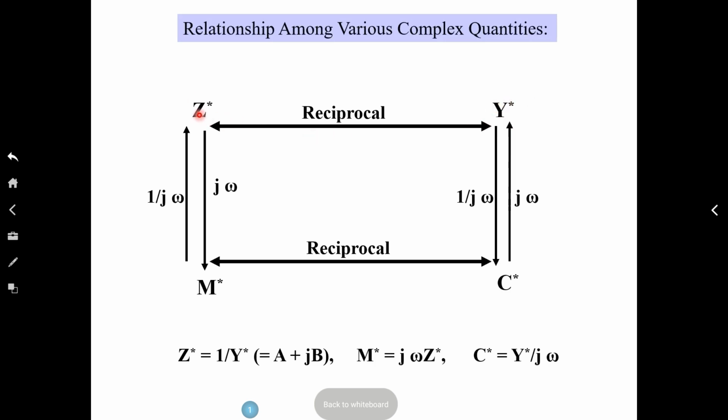It's just the inverse of impedance. So your impedance analysis gives you an impedance vector. You take the inverse of that, that will give you admittance. You can create admittance and then plot the imaginary part of admittance versus the real part. That will be called an admittance plane plot.